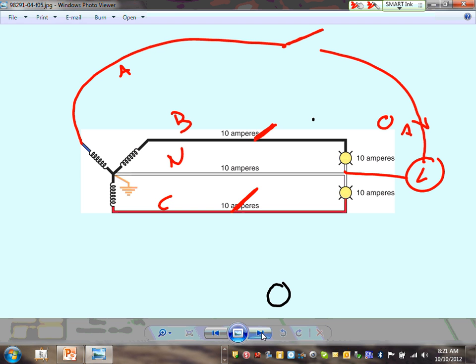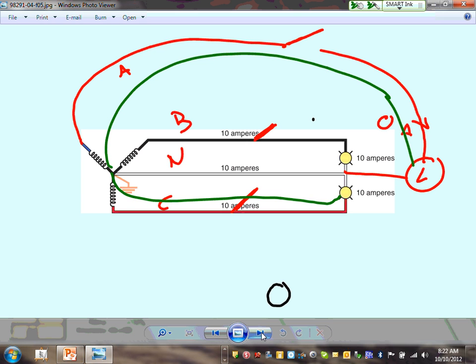From a maintenance point of view, this solves the problem with the most dangerous ones, which are ballasted double-ended fluorescents, because these are the ones that cause trouble. A lot of engineers still specify it that way. On the engineering project that we did, we specified a neutral with whatever phase. So in a case like this, you have to have a neutral coming with every one of these phases going to the fixture.